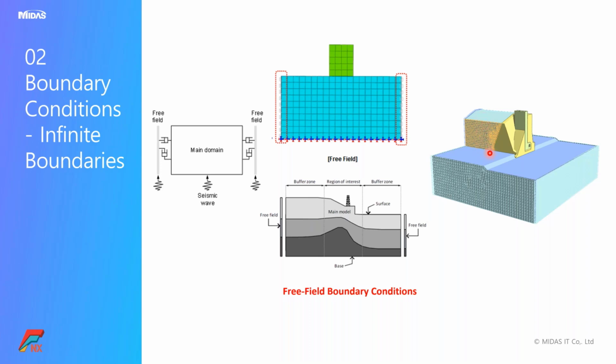The soil cannot stand still over the entire length, I mean entire depth. So hence, we have created some spring conditions here. This spring is also applied with the absorbent boundary as well. So whatever waves are transferring in the backfill will be absorbed in these conditions.